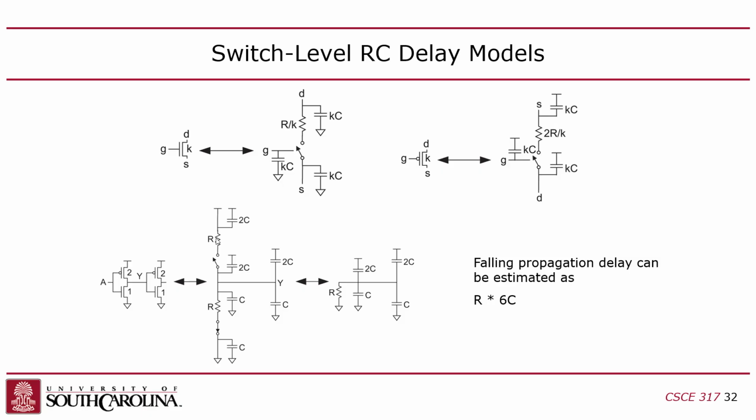So this capacitor counts, this one doesn't. Now, this one also counts because even though this transistor is off, you're still connected to one side of it, and that side of it has a capacitor to VDD. So now I've got a capacitor from the output of the gate down to ground and from the output of the gate up to VDD. So I have double capacitors there, right?